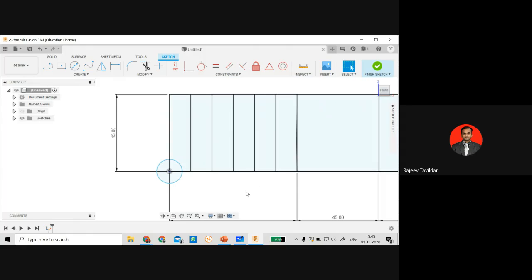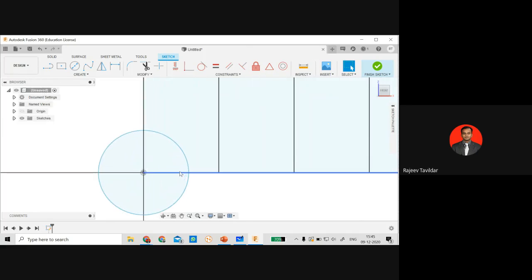The first circle needs to be drawn at the beginning of the rise stroke, which is in cycloidal motion. So this is the beginning point. There I have drawn the circle, and the dimension of the circle we have got by using the equation h equal to 2 pi r. In the next step, we need to divide this circle into 6 parts such that the first division is always horizontal.